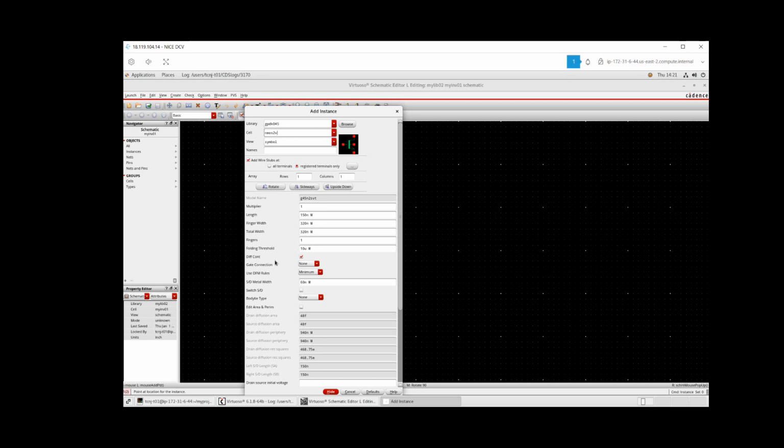Normally in a design you pre-calculate the initial values that you want for the electrical channel width of your transistor, and you can change it here. You can also select the number of fingers geometrically of the transistor, but in our case, for this simple demo, we're just going to choose the default. So we're going to leave that the way it came and place our NMOS over here.